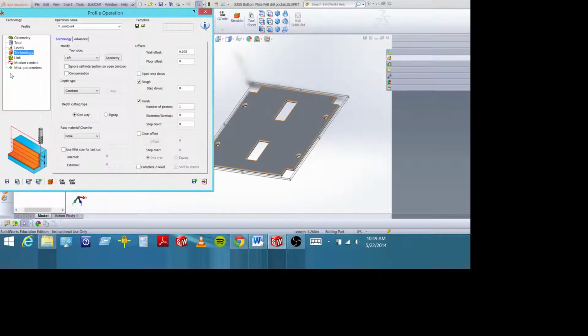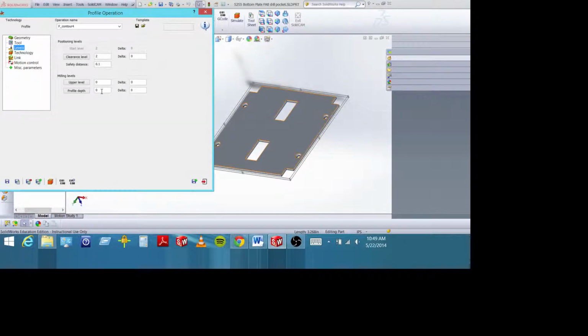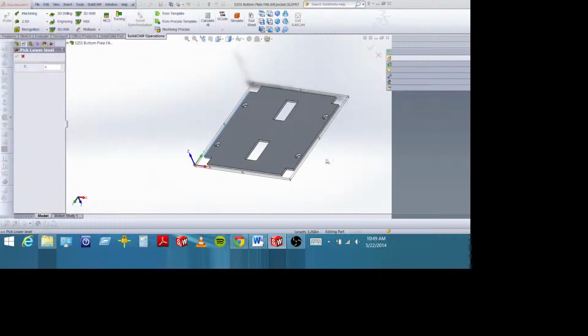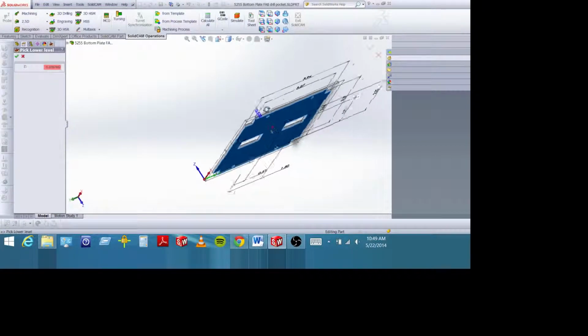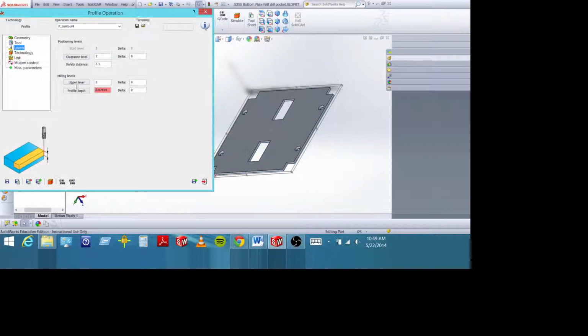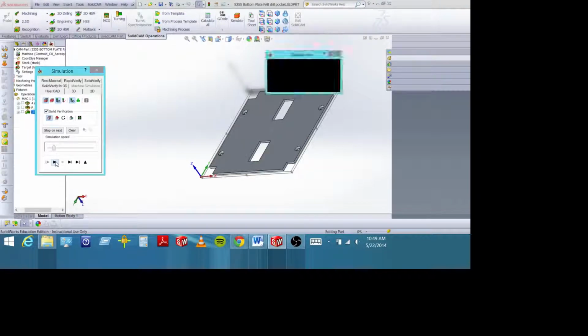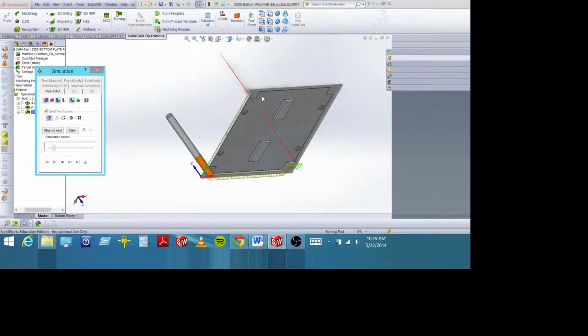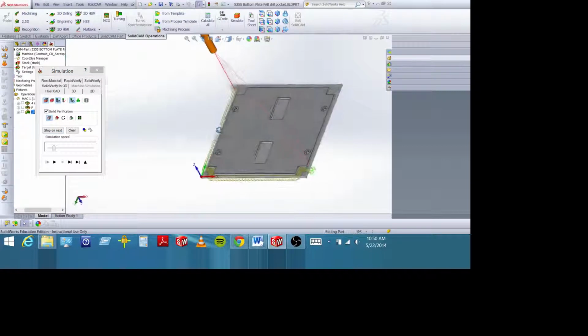Another problem happened. Anytime you reselect geometry, for safety's sake, this CAD program or CAM program, which they all do, is going to set your depth back to 0. So you're going to have to redo that. Alright, let's save and calculate and simulate. Notice that crazy long inch is gone. And it went around twice. Why did it go around twice?